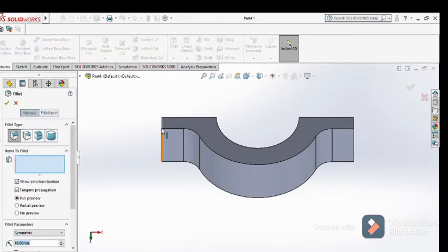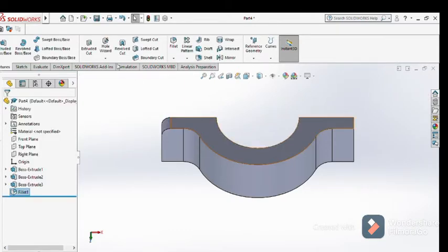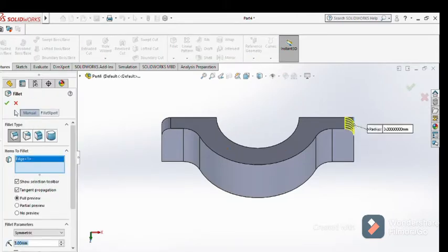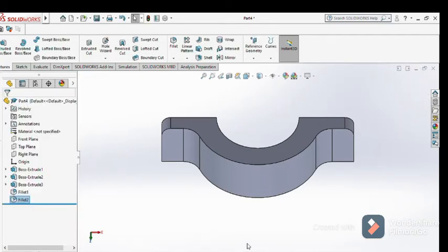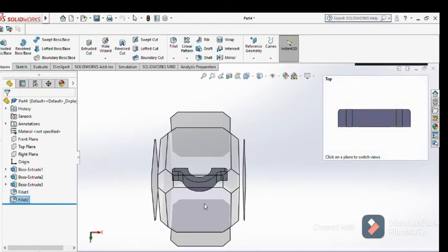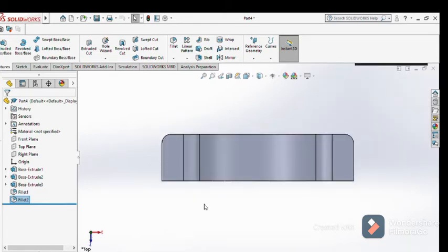Fillet is something that we use to give our corners curves. That's what a fillet does. Let's change our measurements. They said our radius needs to be 3. So just put in 3 there. There you go, and we accept. That's exactly what you want. And then you go again and click fillet. Then you command it where you want to fillet the 3 corners, you accept. There you go. From accepting that, we look again. Let's go back to our top view. There. Now we have something similar to what we were having before.